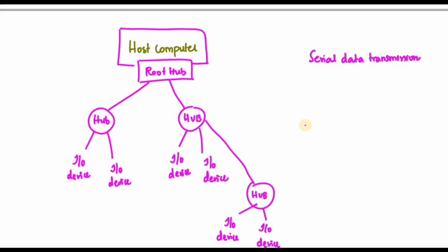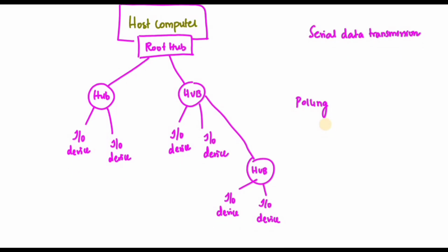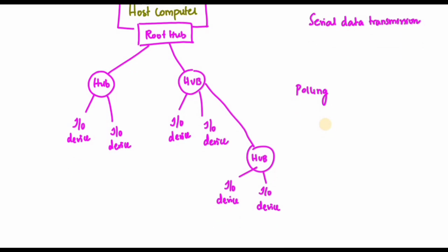Each device on the USB, whether it is a hub or an input device, should be assigned a 7-bit address. This address is local to the USB tree, which is attached to the processor and appears as a single device. The host software will communicate with the individual devices by sending the information to the root hub, which will forward it to the appropriate device in the USB tree.